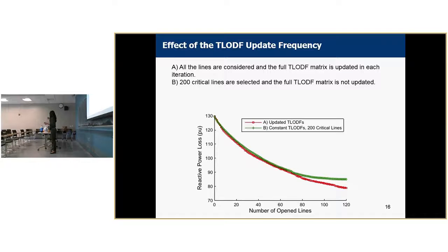We just say if you open this line, it'll change the losses in the transformers this much, and we use just that. But maybe one could be, based on the direction of the electric field, which line has the highest GICs. You'd think they'd be coupled. Yeah, it'll show up in the field, but we don't directly present it like that.